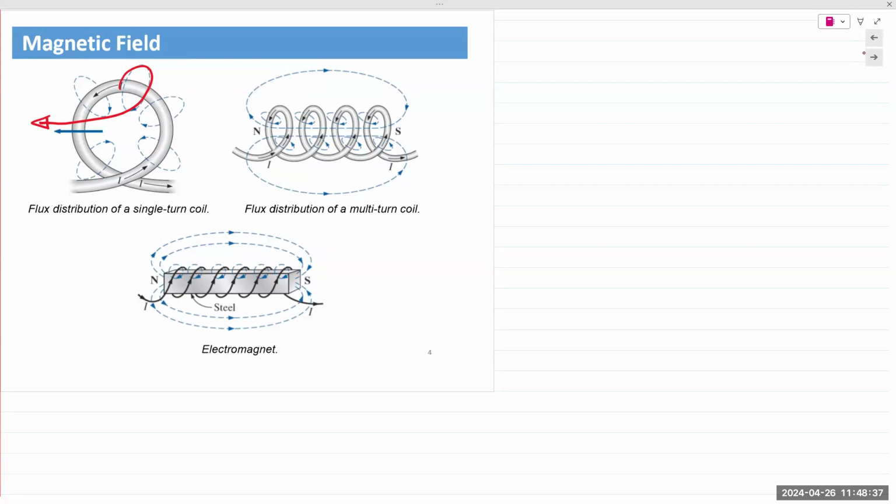If you take that same wire and you wind it up into multiple loops, you will establish a magnetic field that is similar to a magnet. It'll have a north and a south pole. The magnetic flux lines will align, and now the flux lines will flow through the center of that entire coil. The center of that entire coil, the spiral coil, is known as the core of that coil. Again, the field is weak. It is not strong. It, of course, also depends on the amount of current that is flowing through that wire.